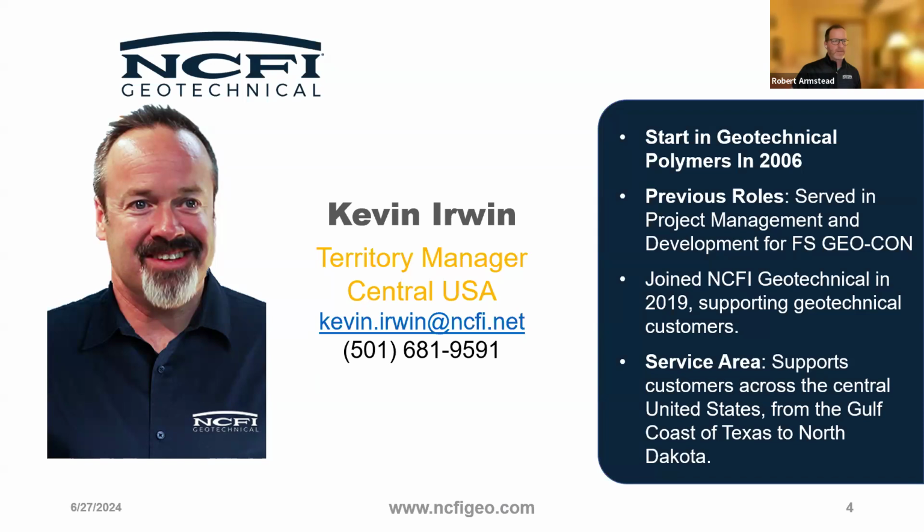Yeah, the only times I've ever seen where they've tried to go through the foam and post was either a mistake or a misevaluation of what was going on in the soil conditions. Or you burn a tube and you don't have an extra. That's the worst, when you didn't sink enough extra tubes down, and now you've lost a tube because it filled up with foam, and now you have to get back down to it. So yeah, that becomes an operational issue.